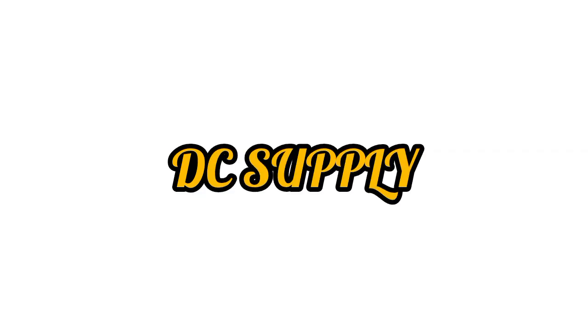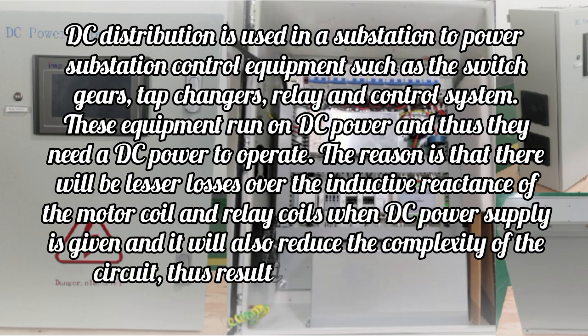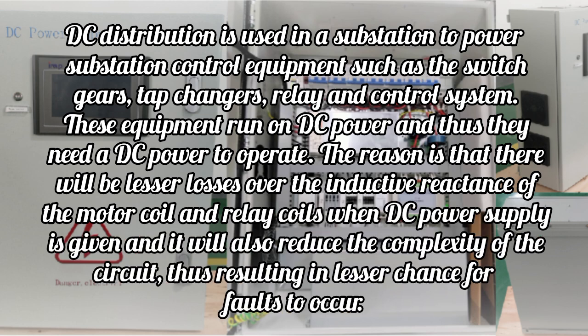DC supply. DC distribution is used in a substation to power substation control equipment such as the switchgear, tap changers, relays, and control system. These equipment run on DC power and thus they need a DC power supply to operate. The reason is that there will be lesser losses over the inductive reactance of the motor coils and relay coils when DC power supply is given, and it will also reduce the complexity of the circuit, thus resulting in lesser chance for faults to occur.